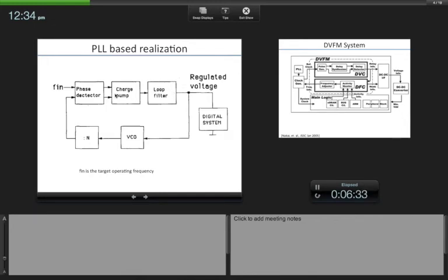Now what happens is that there have been some approaches where even those can be adjusted, but one thing you have to watch out for here is that firstly these are analog circuits, right? Charge pump is essentially a current source which is dumping or removing current from a capacitor, right? That is essentially charge. You're putting some charge, taking out some charge. So the current source is an analog circuit. They have said there is a loop filter here, but there has to be also a voltage regulator which is not shown here, which is similar to what we saw, the op-amp controlling the PMOS. So that op-amp is also analog.